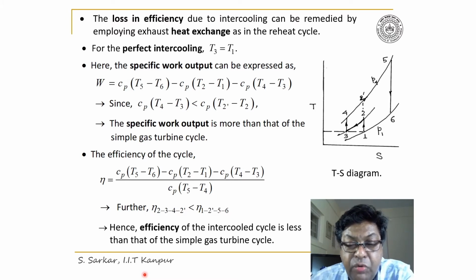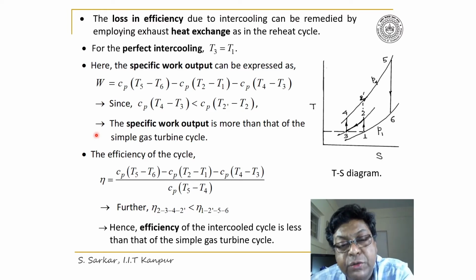Thus, some work has been saved because of intercooling, and thereby the specific work output for the intercooled cycle is more than that of the simple gas turbine cycle.